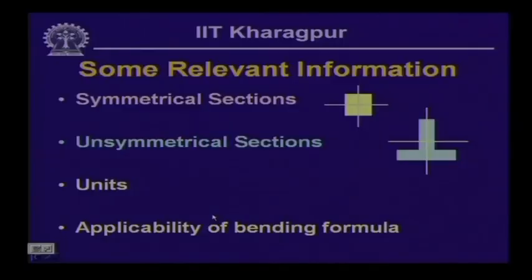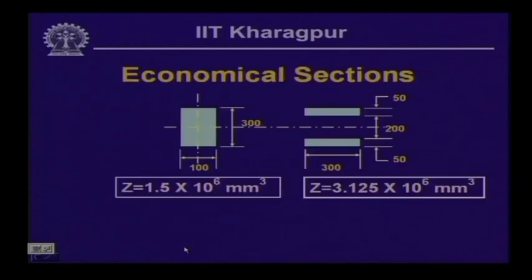If the bending is non-uniform, even then we can employ this equation without losing much accuracy in the analysis of the stress. So, this is very important: though we derived the equation in terms of pure bending moment, we can apply it in other areas as well, where the beam is not truly acted on by pure bending.